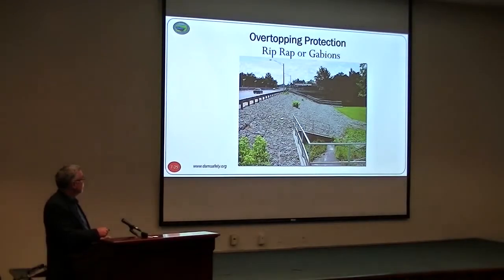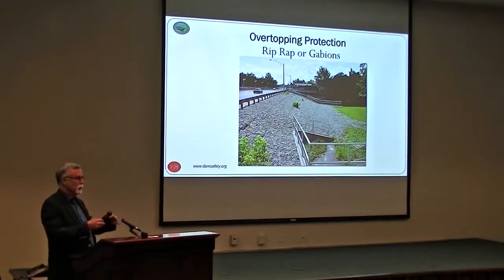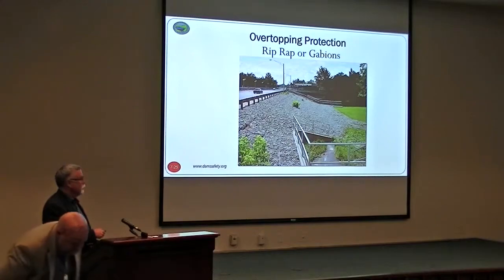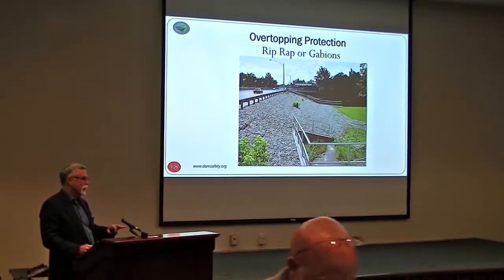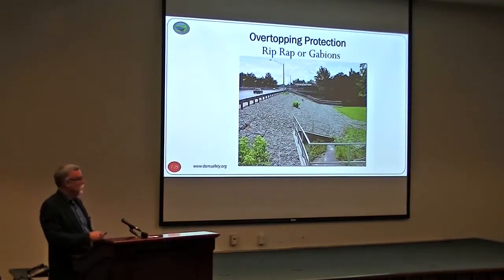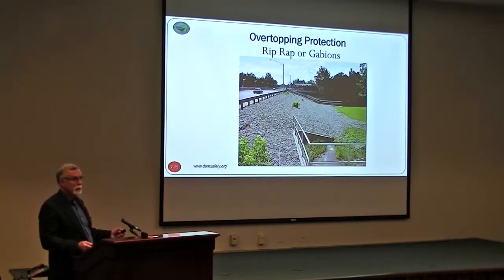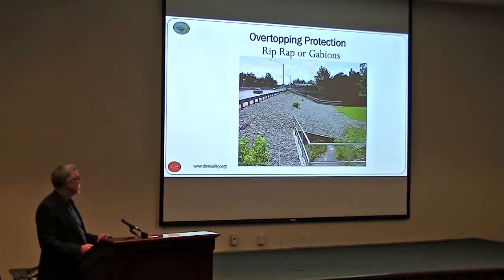Gabions, this is one. Gabions are wire baskets filled with stone, like 6-inch stone and a little smaller. And you see on the back of this dam, these wire baskets are galvanized wire, so they'll last 15, 20 years. But then eventually they'll corrode, and then now you just have loose gravel on the back of the dam. So a limited lifespan. The concrete articulating blocks and RCC will last decades. This has a limited lifespan. Some states won't allow it because of that, because they know you're going to have to replace it in 20 years.